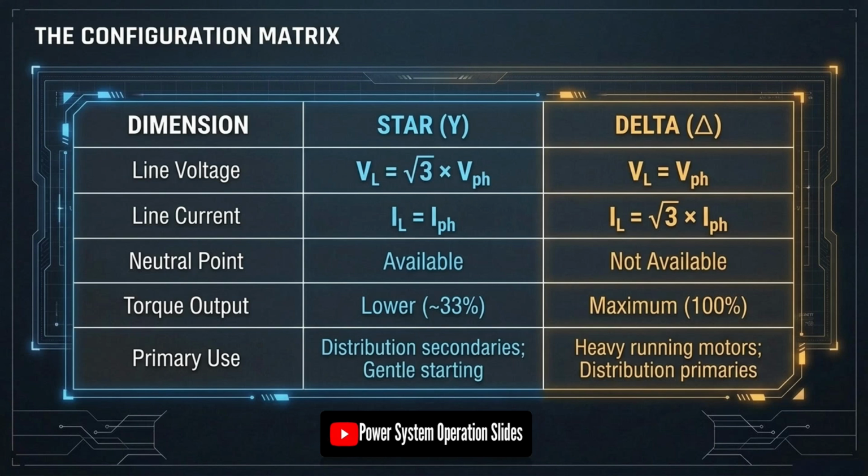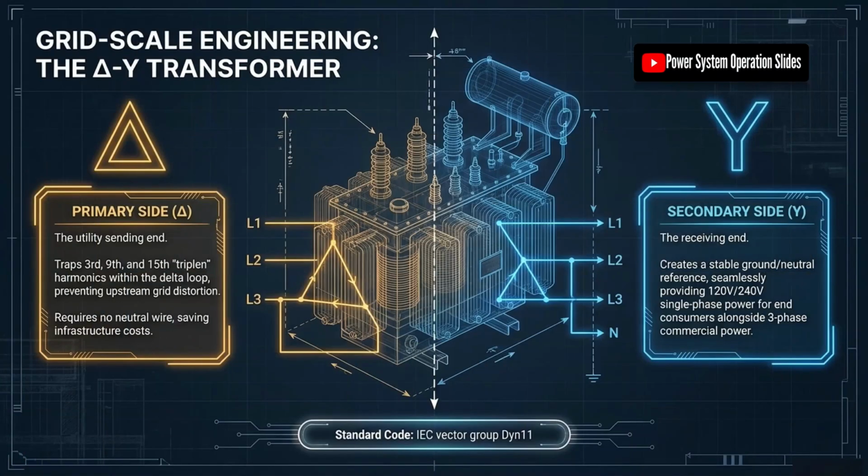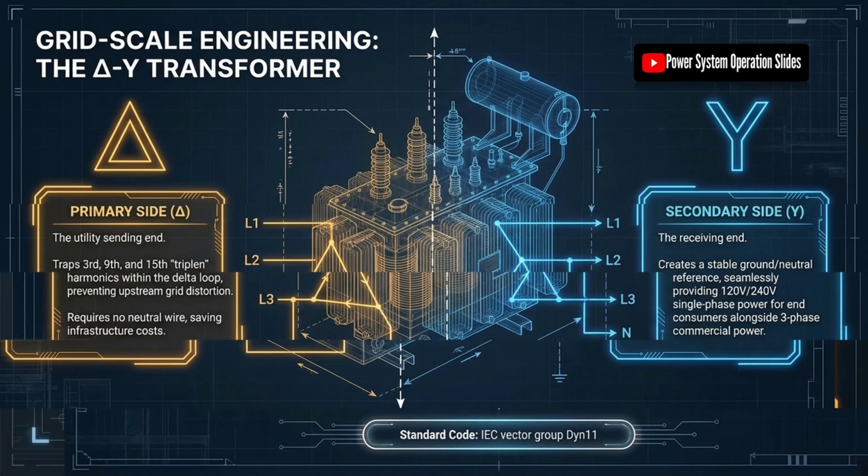Full line voltage is then applied to the motor windings, allowing the motor to develop its normal operating torque and continue running under rated conditions. This method provides a relatively simple and economical method of reducing motor starting current and voltage disturbance, although it may not be suitable for loads requiring high starting torque.